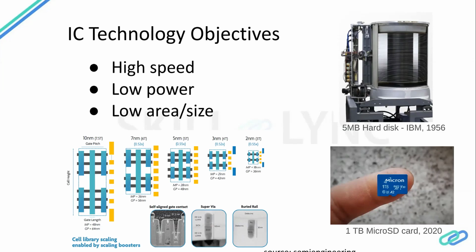When it comes to VLSI, there are certain terminologies that are used. IC fabrication technology progresses from one process node to another. Each process node is denoted by the smallest element in the transistor, or the size and length of the gate, which is usually in nanometers. It can be 22 nanometer, 14 nanometer, 10 nanometer, and so on. As the technology advances, the size of the gate also reduces, right? Right now, in 2020, the process node is around 7 nanometer, 10 and 5 nanometer. Going forward another 2 to 5 years, it will reach up to 2 nanometers.